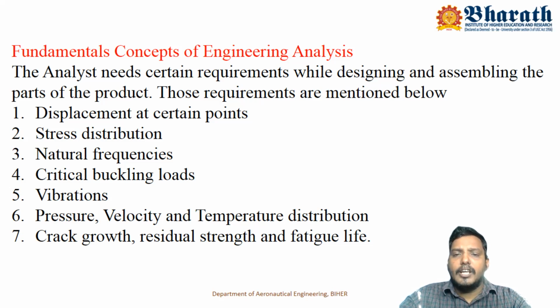In the finite element method, we need to follow some general steps. One, we describe the structure as a convenient number of elements. Then we assign node numbers to the elements. Third, we develop a finite element equation for individual elements. Then we assemble them to get the global finite element equations. Once we get the global equation, we apply the essential boundary conditions. After applying them, we get simultaneous equations, and solving them gives the solution of the problem.